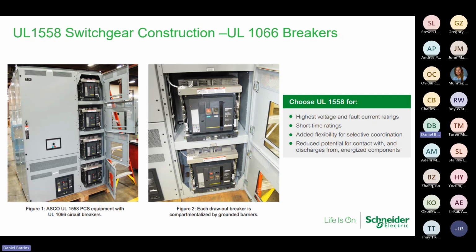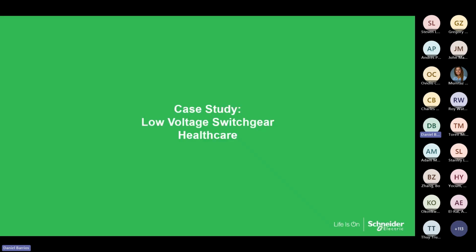Typically we're at 3 electrical cycles, 0.05 seconds there, but depending on how your coordination is, that transfer switch may be exposed to that fault for beyond 3 cycles. We understand that, but you may not have to take that all the way out to a 30 cycle rating. We want to discuss that with you if that's something that we need to clarify for you.